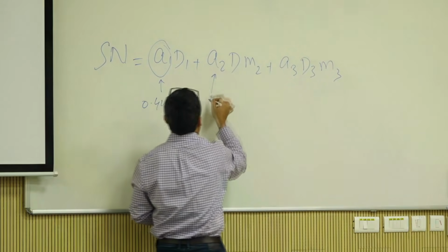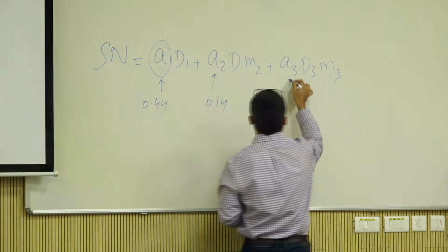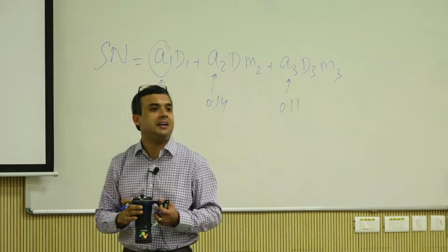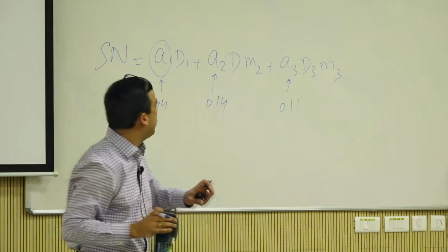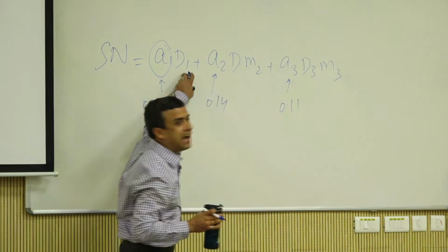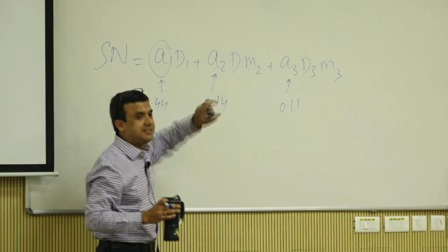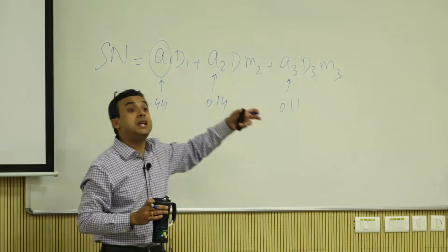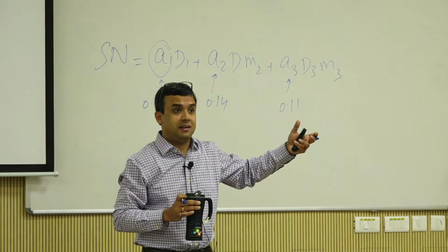And for base and subbase it is something like 1.08. So you are saying every inch of asphalt has this structural coefficient of 0.44. So if it is 2 inches, it is 0.88, right?